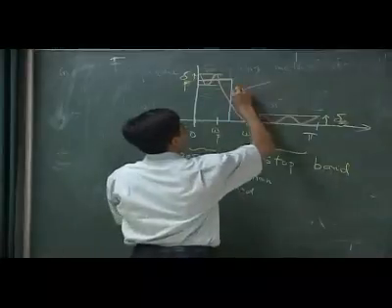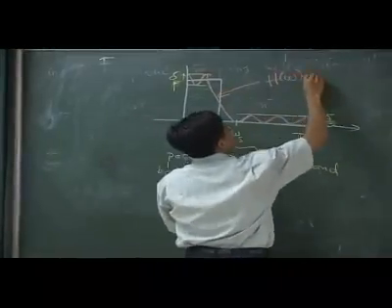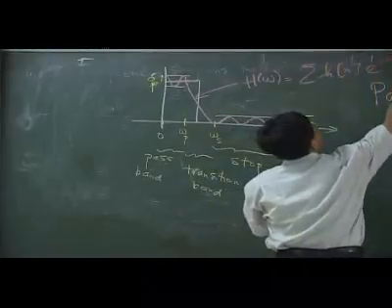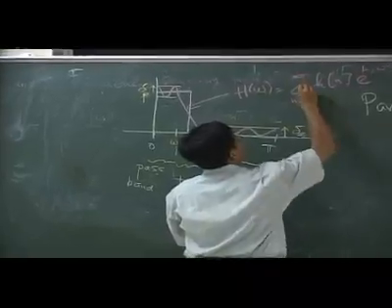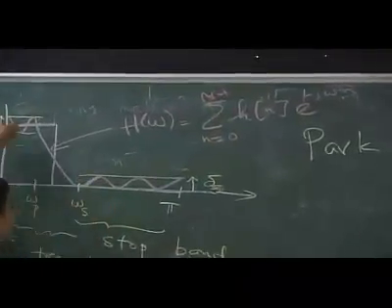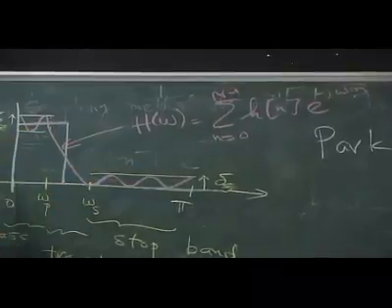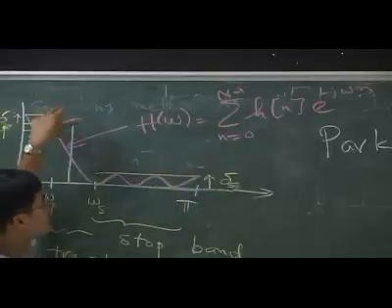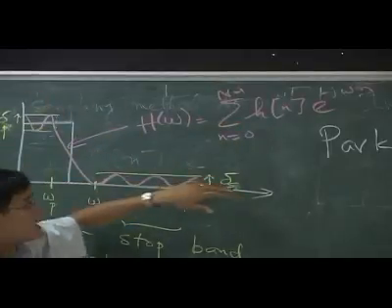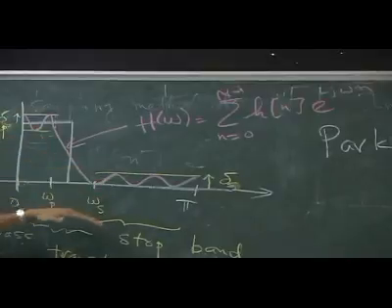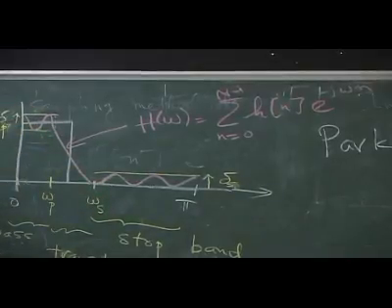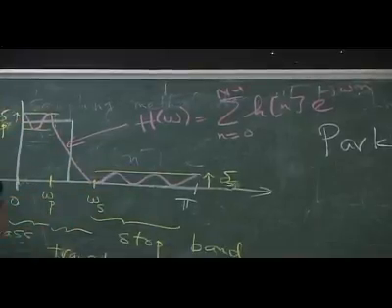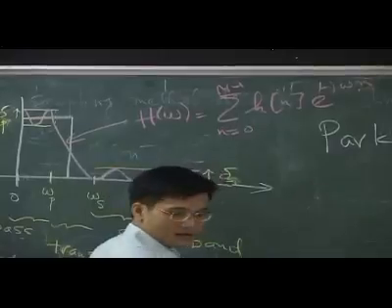So this thing here is the function H(omega) that can be written as the summation of some h[n] e^(j omega n), and n goes from 0 to N minus 1. So this curve here is, even though it's a function from 0 to pi, controlled by only N degrees of freedom. And here you see that actually it is a polynomial. And because it's a polynomial and you really force them, actually in the optimal case, you're going to hit all of these boundaries. So this filter is going to be the solution.